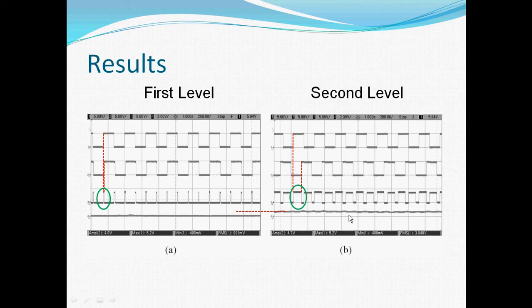The third track is the output of the phase detector, and the last track is the output signal of the low pass filter. Note that when the free end of the water hose is set higher than usual, the duty cycle of the output of the phase detector increases and the voltage output of the loop filter also increases, which is amplified to drive the pump.